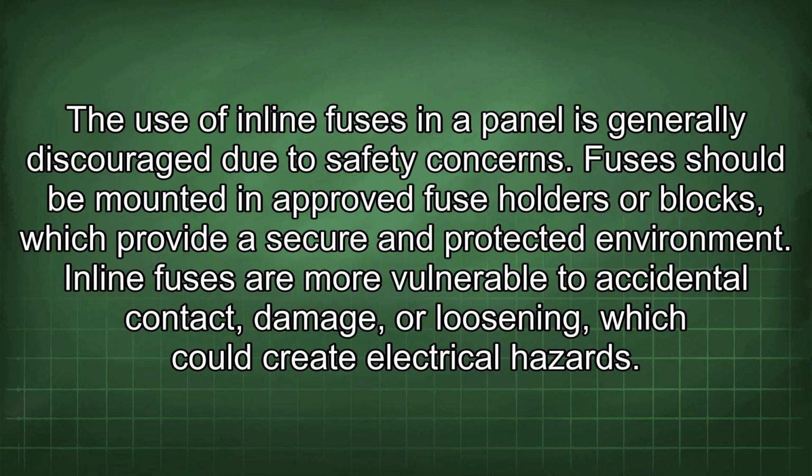The use of inline fuses in a panel is generally discouraged due to safety concerns. Fuses should be mounted in approved fuse holders or blocks, which provide a secure and protected environment. Inline fuses are more vulnerable to accidental contact damage or loosening, which could create electrical hazards.